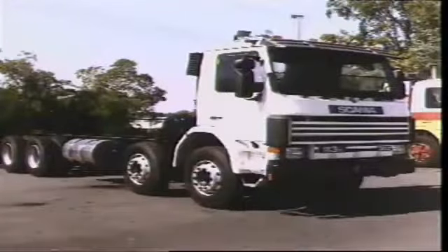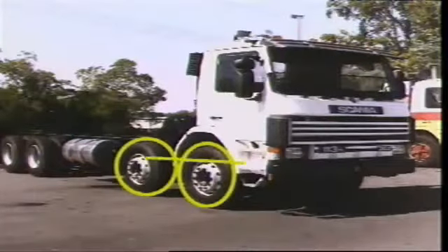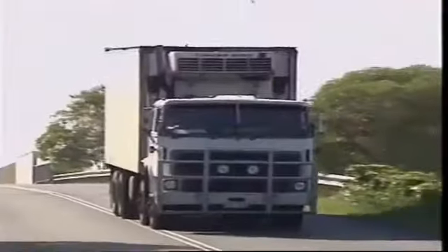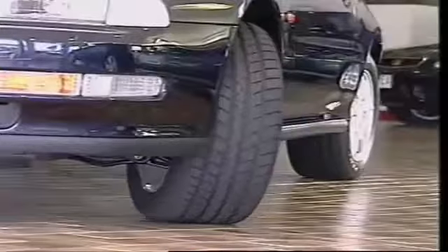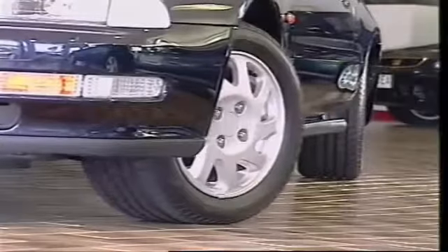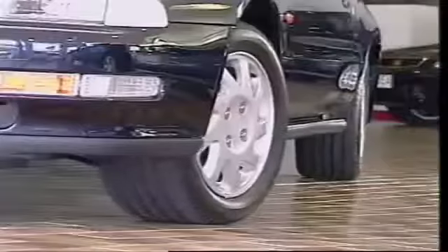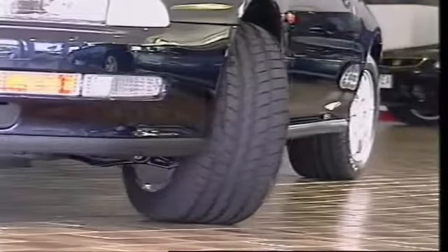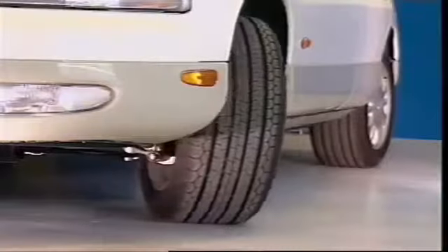To allow the heavy transport vehicles to carry extra weight, two steering axles may be used. They're connected by a link to a common steering box. These vehicles are called tandem or twin-steered vehicles. Some passenger vehicles also steer the rear wheels slightly. This gives improved maneuverability. The system is known as four-wheel steering. It can be controlled mechanically through a direct connection between the front and rear steering boxes, or it can be computer controlled.